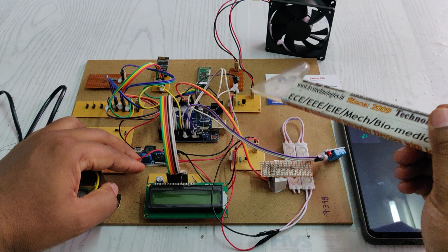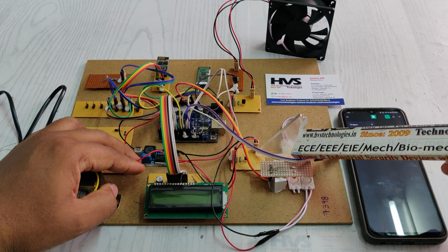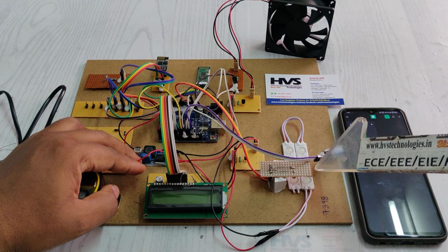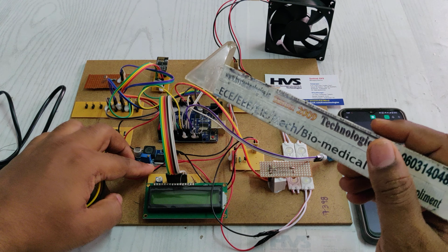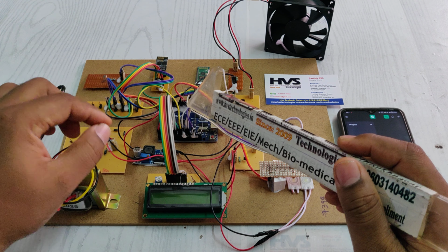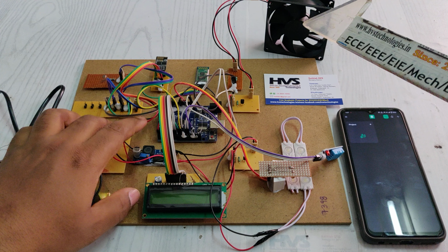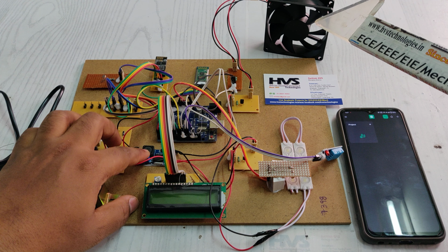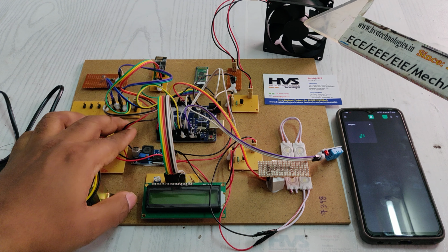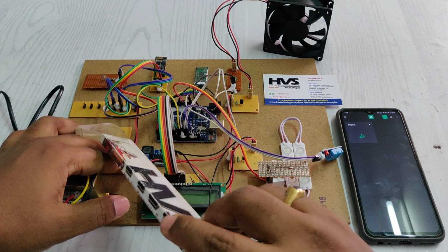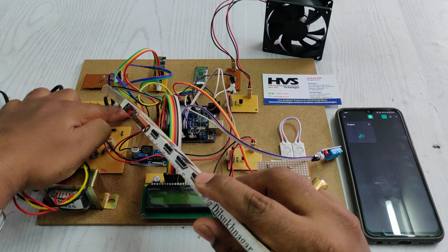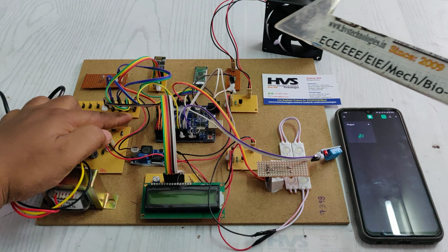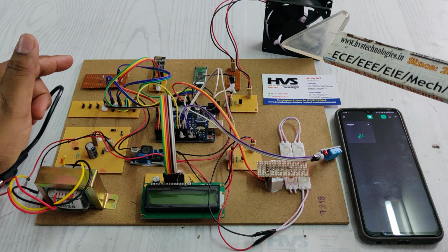This is a switching device to control the fan, and this is a BC547 transistor switching device to control the LEDs. The operating voltage of our Arduino Uno, which is the main processing unit, is 5 volts, and for that purpose we are using an LM2596 voltage regulator, which provides a 5 volt DC output. The DC is input to the breadboard, and from there the voltage is distributed throughout the input and output modules.